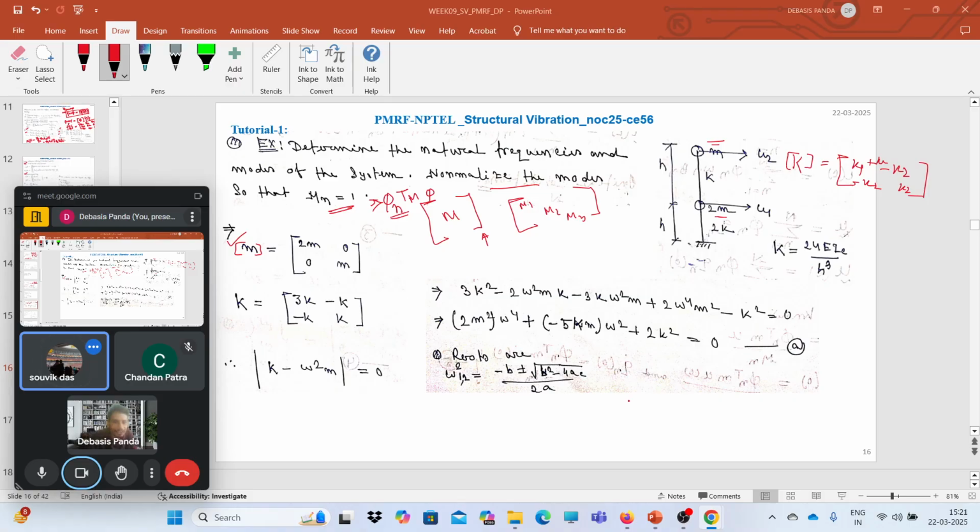Yes. So for the K matrix, if you forget it, I recommend you recall this pattern of the matrix, so it will be easy to solve this problem. The structure of the K matrix for a 2 degree of freedom system looks like K1 plus K2, minus K2, minus K2, K2, right?